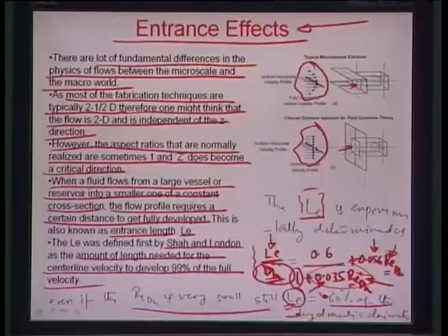You need to wait until the whole entrance length needed for developing the flow fully is traversed before the flow can get into a region where significant differences can be made to it by changing the physical form or shape of the microchannel. So definitely entrance effects are very critical as far as microfluidics are concerned.